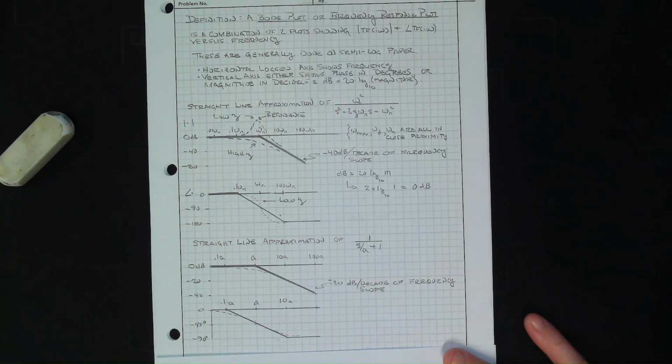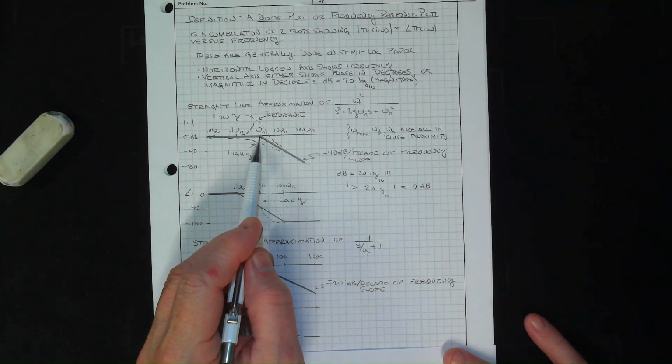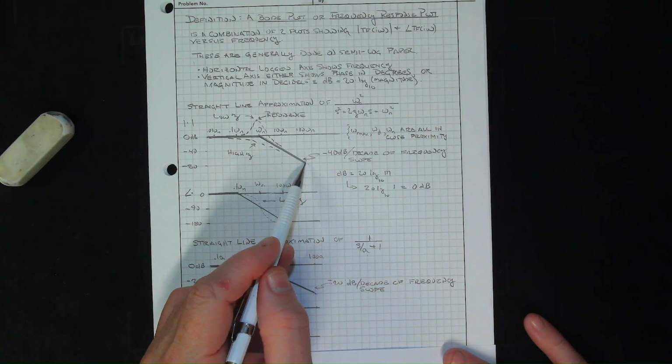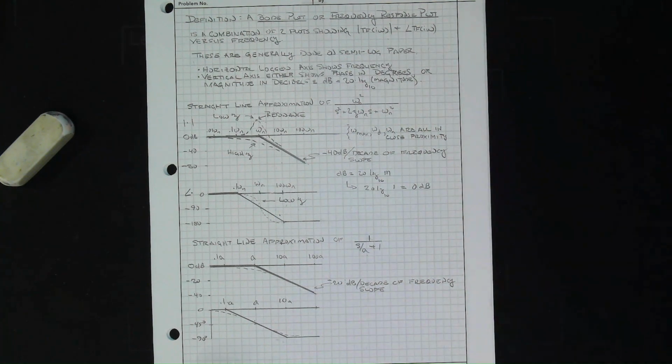As you get to high frequency, at some point, it just can't keep up. And so as you pass through the natural frequencies of the system, it's saying, I can't keep up anymore. That's what you're seeing. Now, when I say mechanical systems are low-pass systems, I'm talking about you. You are a low-pass system. We're going to prove that right now.